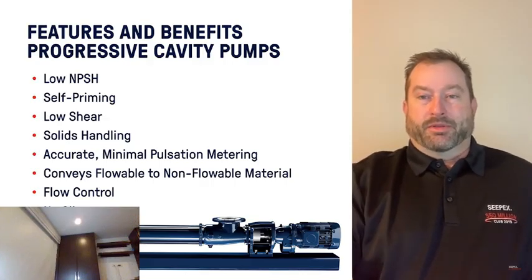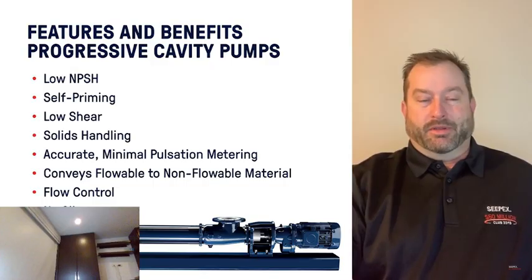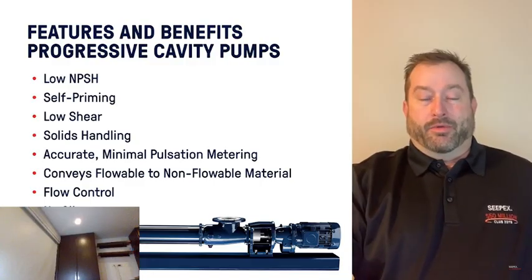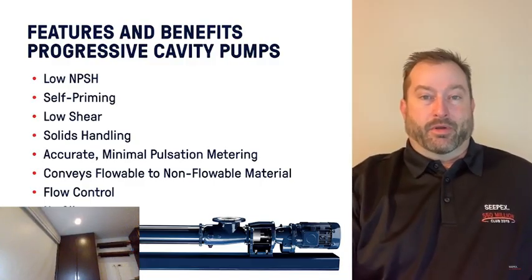We do single and multi-stage, so you can actually get very high pressures out of these pumps. They can also operate on very thin liquids as well as very high viscosity liquids. We pump everything from water or alcohol, which is very thin, up to dewatered sludge cake.